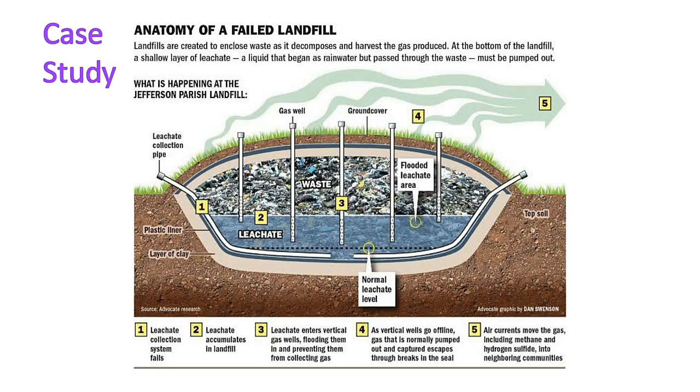Friends, I have a case study here. It is the parish landfill. Okay, they have given the anatomy of a failed landfill. What happens exactly if a landfill fails, even if a minor part of it gets damaged? What are the major effects it may cause? See, even here they have mentioned the definition: landfills are created to enclose the waste as it decomposes and harvest the gas produced, right? At the bottom of the landfill, a shallow layer of leachate is going to be developed. Fine. A liquid that began as rainwater but passes through the waste must be pumped out.